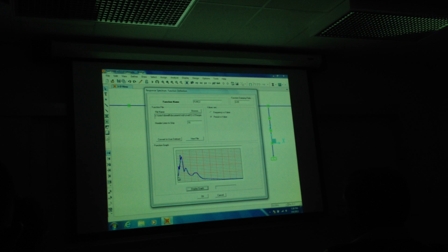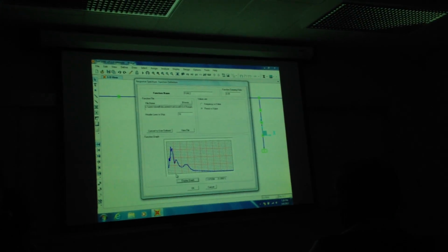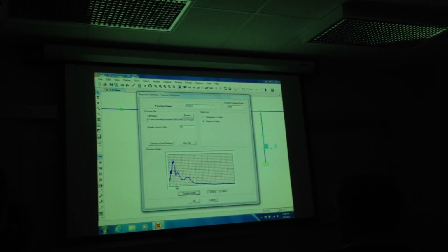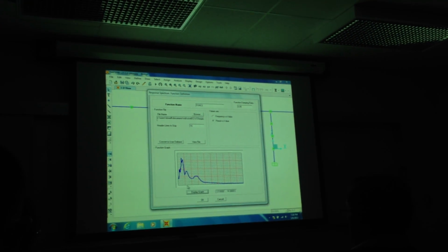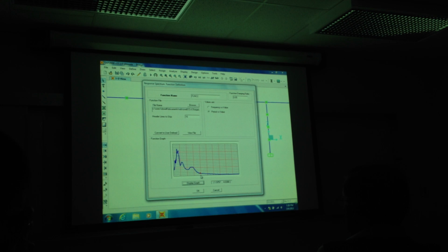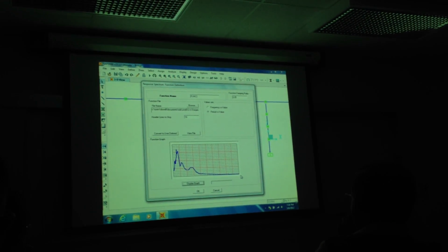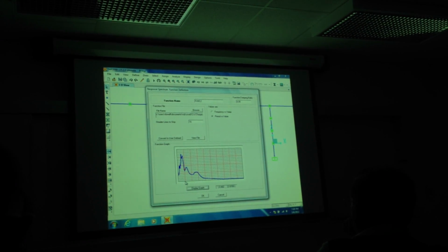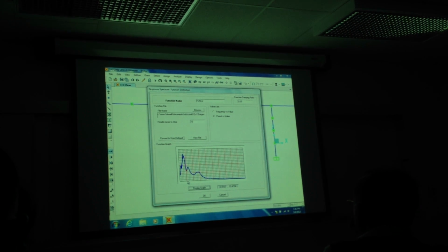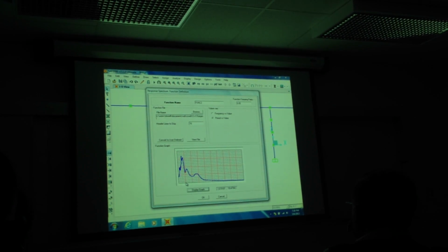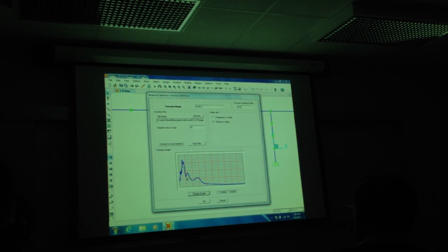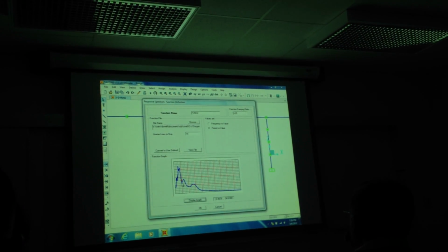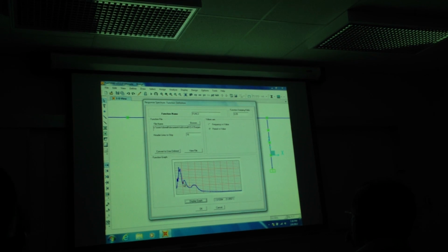Now let's say you have a more flexible structure, let's say about here. This point there is the acceleration for that period of structure. So here we're at, let me see. It goes all the way to 5 seconds. So at this point, let's say right here, the first number here is a period, natural period of about 0.5 seconds. And then it's 19, so it's a little more than 0.5 g acceleration at this point. That's the acceleration, absolute acceleration of the structure. Mass times acceleration is the force that goes into the column. So it's proportional to that.